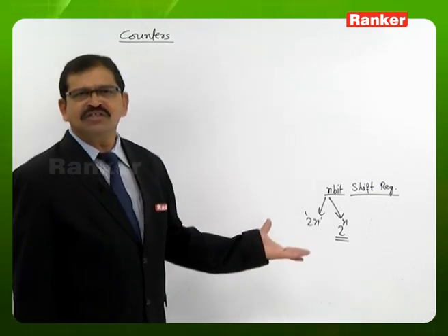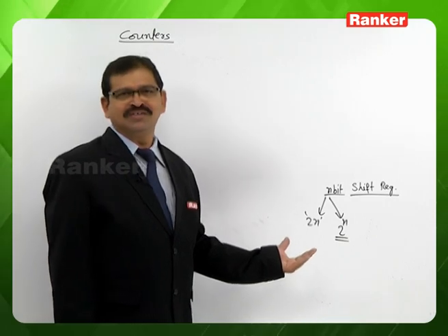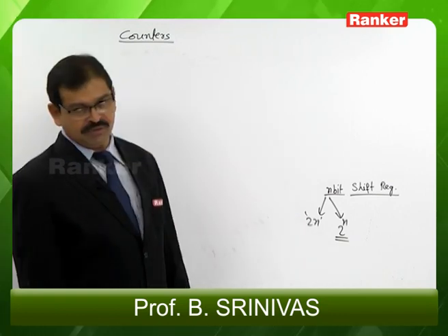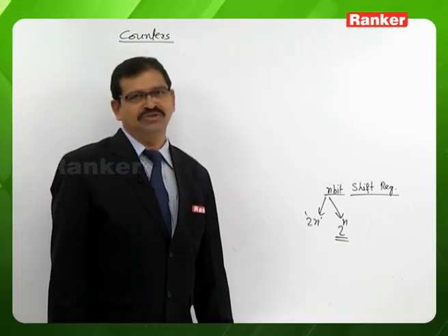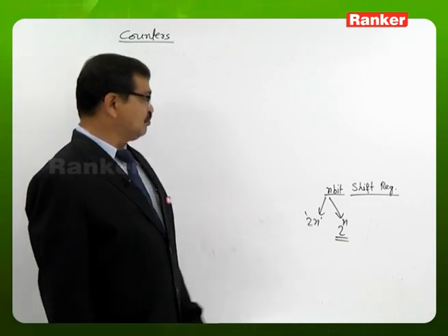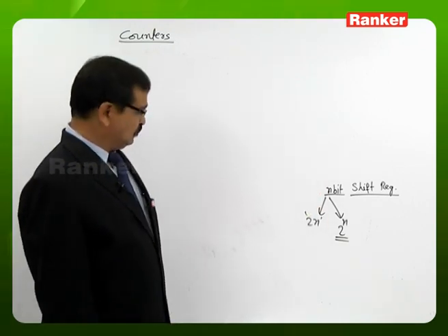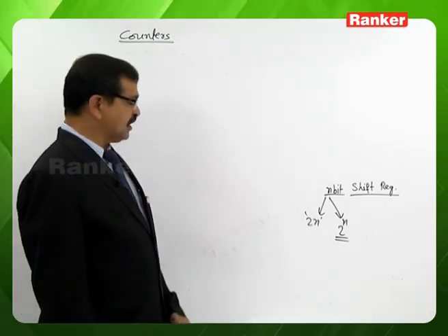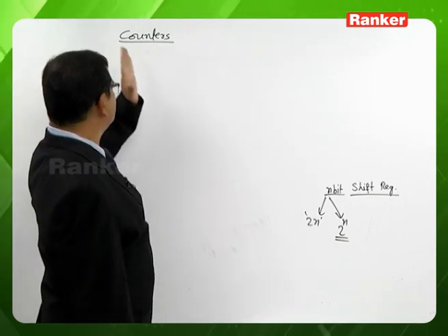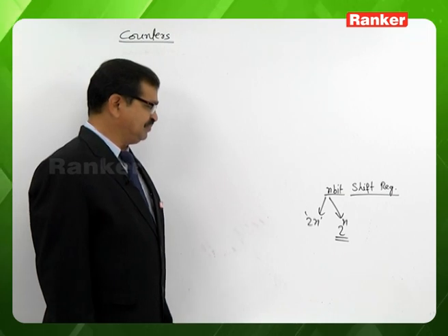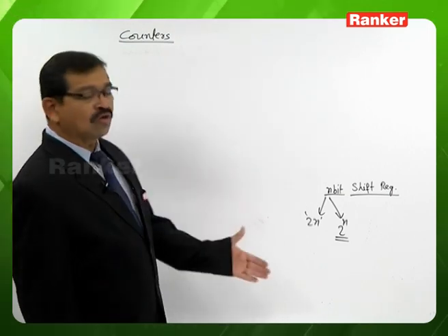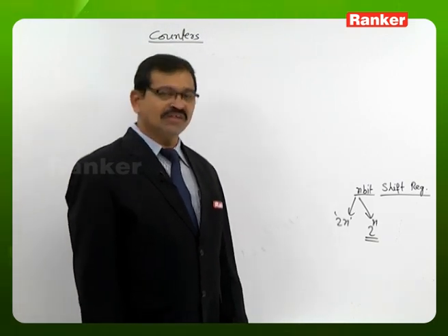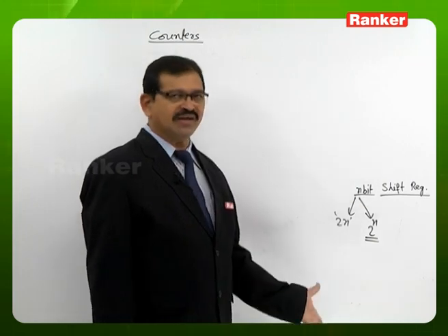Of course, a register is basically developed as a storage device. As an extra application from the storage device, from the register, we have this counter operation. There are specially designed circuits. In these specially designed circuits, with a group of n flip-flops, we have the possibility to count 2 to the power of n clock pulses. These specially designed circuits which are used for counting clock pulses, we name as counters. So if you want to count 8 clock pulses, then no need to use 4 flip-flops. For counting 8 clock pulses, only 3 flip-flops are enough.